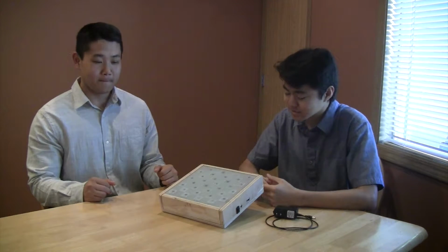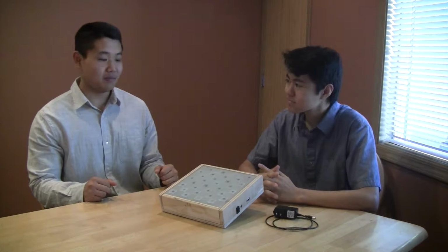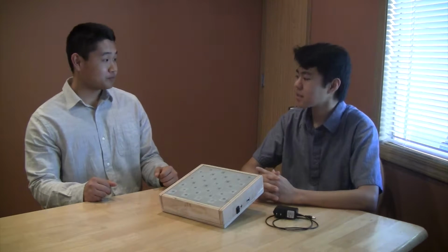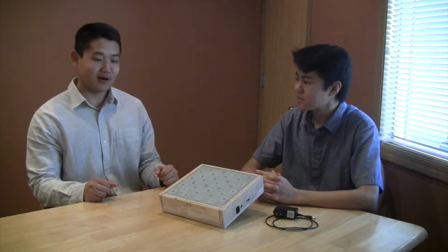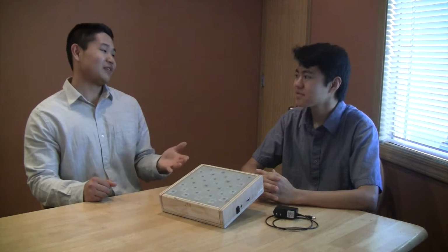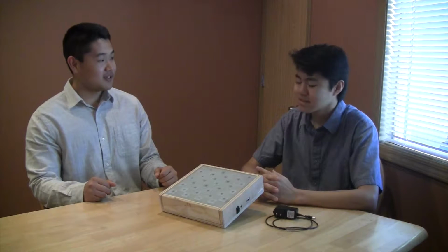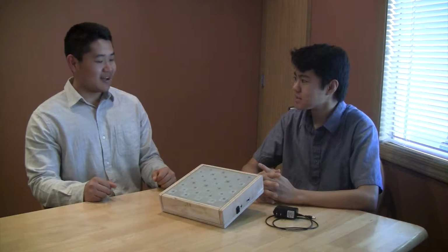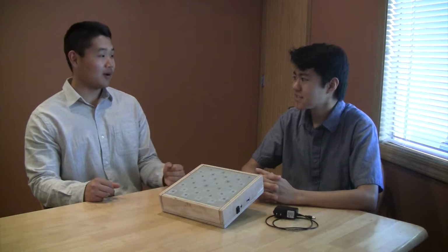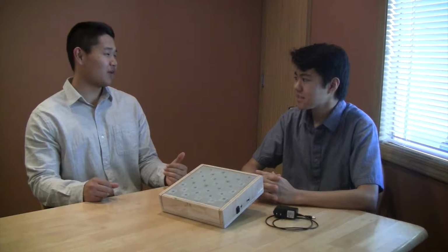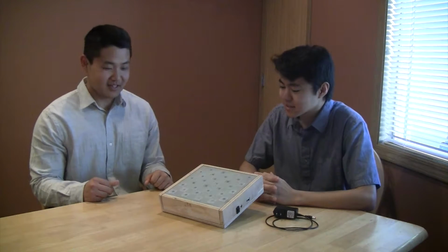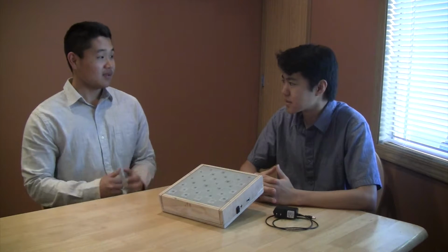So first I attempted it using a software known as Eagle that's provided by the school. And I came across the problem of not knowing as an amateur that the school only provided the light version. So what would that cause? Well, I come to find out that we could only generate a board that was maybe 1/4 the size of what we needed. Oh, yeah, that'd be a problem. Right. So how did you get around that?